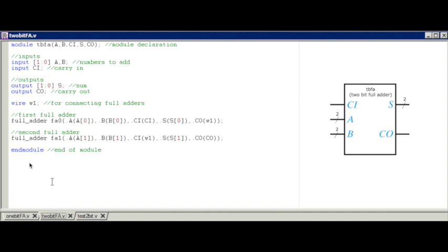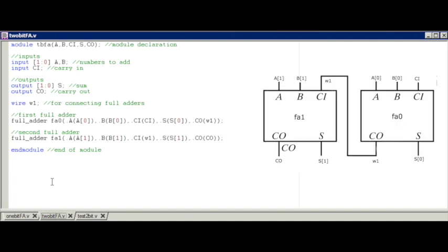But now I'm going to show you a picture that will help you internalize a little bit more what we've done. To your right now, there are 2 1-bit full adders, and each one of them has the respective instantiation name. And notice how in full adder 0, the first bit of A and B are input along with carry in, just as we've done here in Verilog.